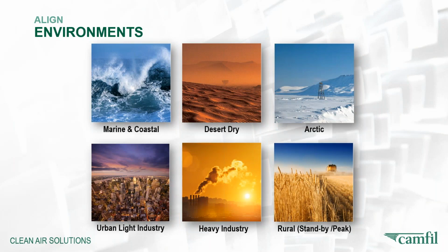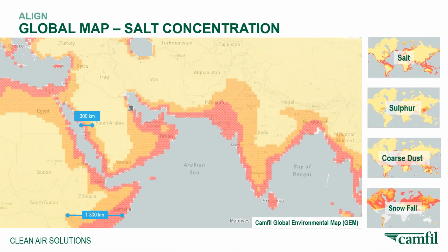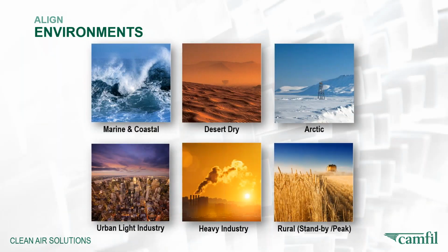So if we take a look at the extreme environments throughout the world, it's pretty safe to say that when designing an inlet system, one size does not always fit all. If you consider the marine and coastal environments, you have materials such as stainless steel construction, multi-stage performance, as well as focusing on salt removal to eliminate hot corrosion. When we look at the desert, very, very high levels of dust, meaning a self-cleaning pulse filter is often followed by a high efficiency static HEPA efficient filter.